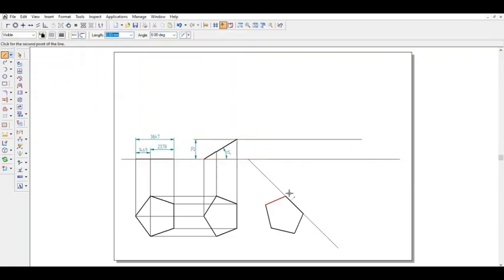So these two sides are here on the projection lines. So you'll get 2 points here, another 2 points you are going to get here. No need of drawing this, you cannot go for longer lines, you can just have the shorter ones, whichever is necessary, wherever it is necessary, till there only you can draw this. Again go for line. I know these 2 points are somewhere on this one. So I'll project this. I know it is on this particular point here. Similarly this one also is here, so I have to show the projection here.